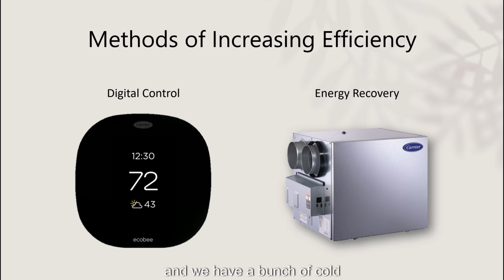However, if it's the middle of winter and we have a bunch of cold air coming in, well, that's going to take a lot of energy to heat that up, right? Or we're going to be blasted with some subarctic weather sometimes. So the energy recovery ventilator will actually transfer the outgoing heat content that's in that air, mix it in with the incoming, and now all of a sudden the air is more tepid, right? It's not going to have that big temperature difference, that big fluctuation. It can also transfer humidity as well. So now all of a sudden we're not going to have dry air. So energy recovery ventilators, they're really great pieces of equipment.